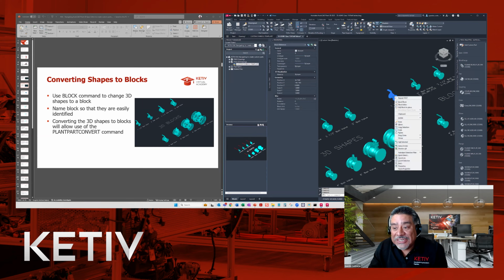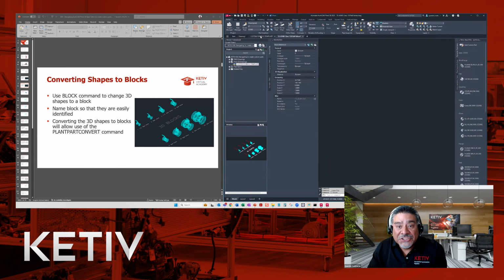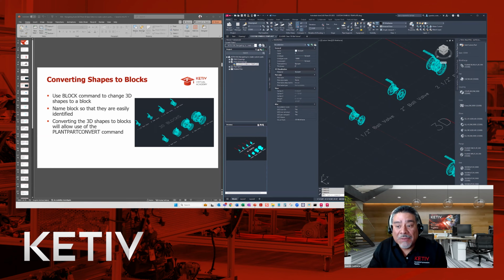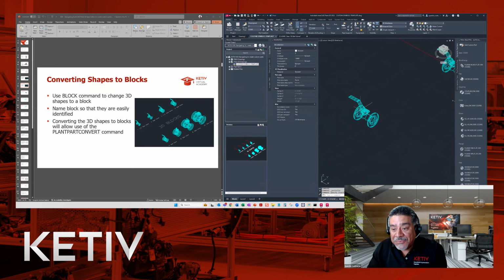So I'm actually going to take this one and I'm going to copy this one. So I'm just going to select it. I'm going to do a Control C to copy clip. I'm going to jump back to this drawing because this is part of my project and I need it to reside over here. And then I can just Control V that one there and put that in here. So as you can see, when I go over this one, it's a block reference. It's not a solid surface reference here.